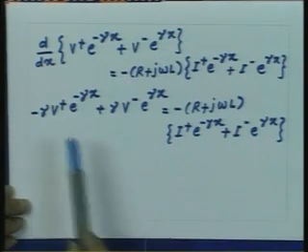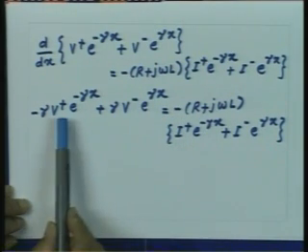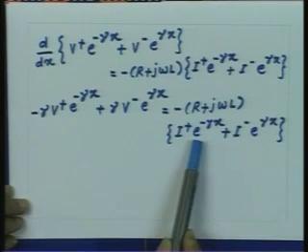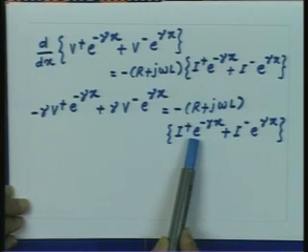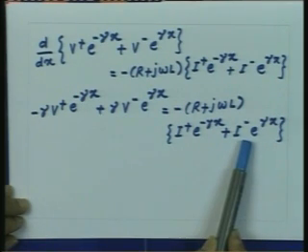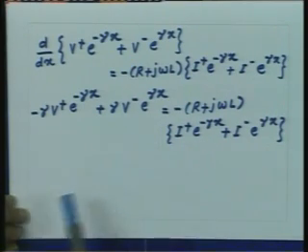What that means is that within this one equation there are two embedded equations. The forward travelling wave, which has V plus amplitude, should be related to the forward travelling wave for current. Similarly, the backward travelling wave for voltage should be related to the backward travelling wave for current. So, from this one equation you can get two equations, because both the waves have to satisfy the differential equation individually, since the voltage and current expressions should satisfy this condition at every point on the transmission line.